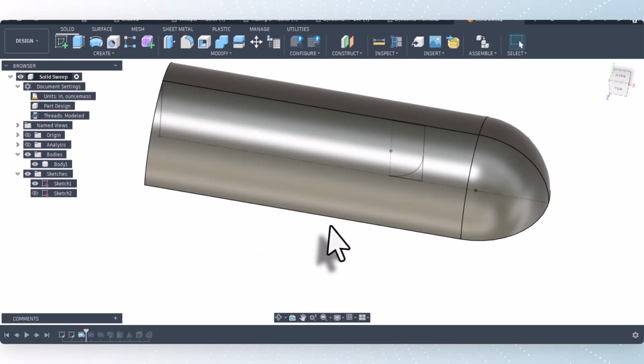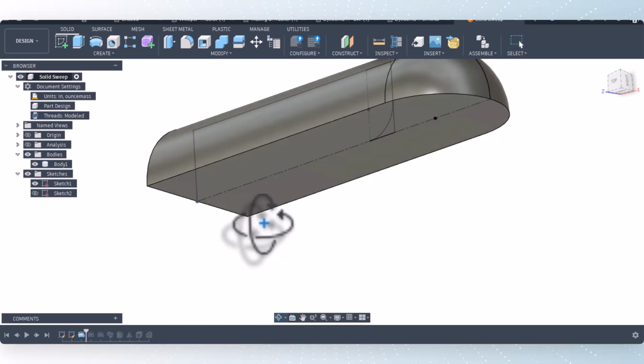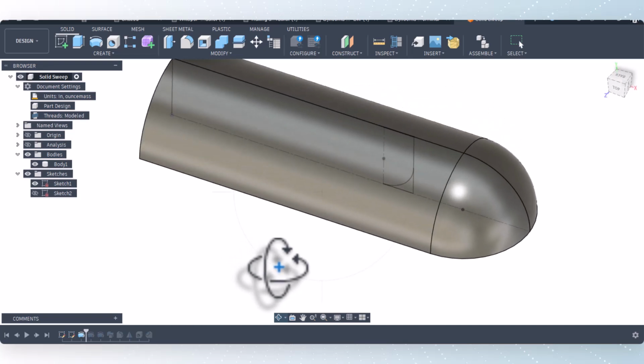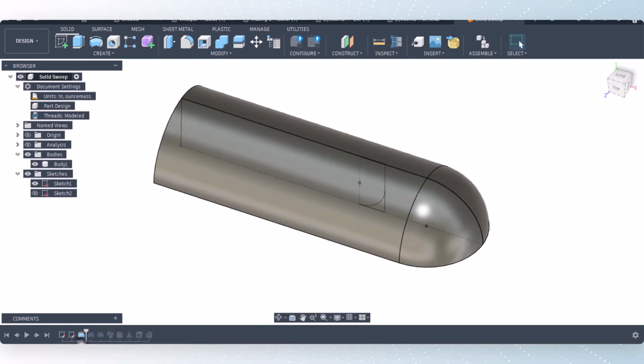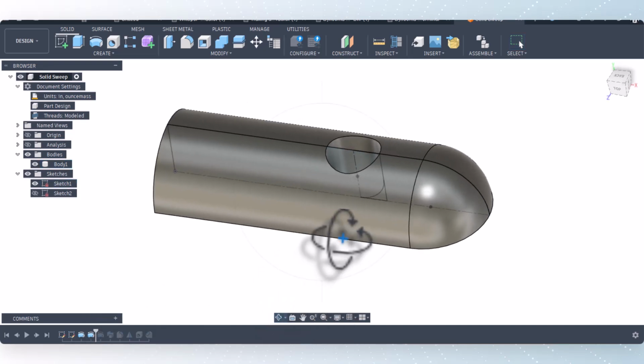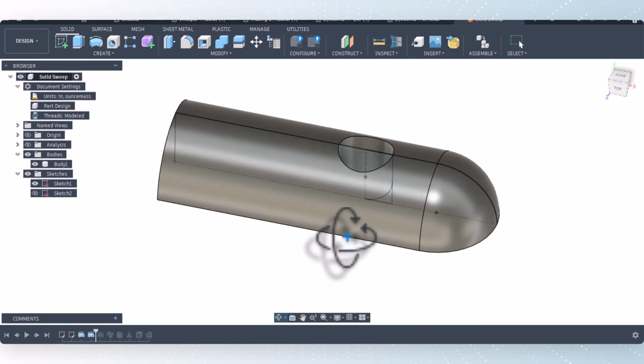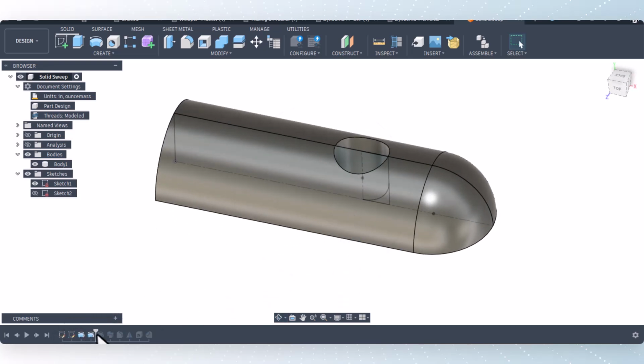So I turn the end mill. Now I'm only going to do one half of it, and then we can mirror that body so we can save computational resources by only modeling one half and then mirror. So then I'll drill a hole through the part, okay? And same way we would do it in manufacturing, we would go ahead and drill that hole through.